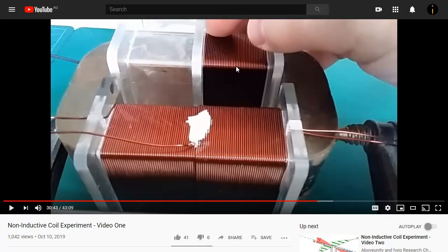Okay, so the input coil over here, the input current was reduced to approximately half when this coil over here was in bucking mode. So you could say that the bucking on this coil reduced the whole system through the core, because you've got to remember that these coils are all magnetically coupled through the core, and therefore the coupling in the coils changed the impedance of this coil.